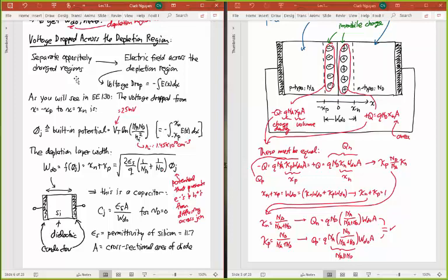across the junction. Okay? Now, I've already alluded to the fact that this is a capacitor. It's a capacitor because it's charged. And this charge is controllable by this potential. Right? And so if I add more voltage in this potential, which I'm going to do a bit later, I'm going to modulate that charge, which means the amount of charge that I have here can be a function of the voltage across this. But in the end, just the fact that I'm developing two different charges there says it's a capacitor.